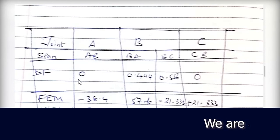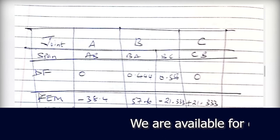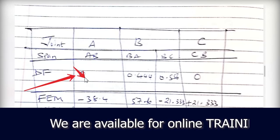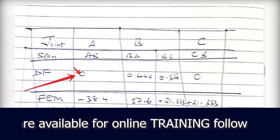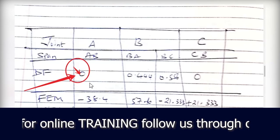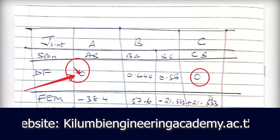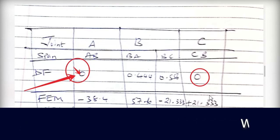Now, the distribution factor at support A, which is a fixed support, is always 0 for a fixed support, and also on the right hand, the distribution factor at support C is 0 because it is a fixed support. But support B distributes to two members, member BA from the left and member BC to the right.